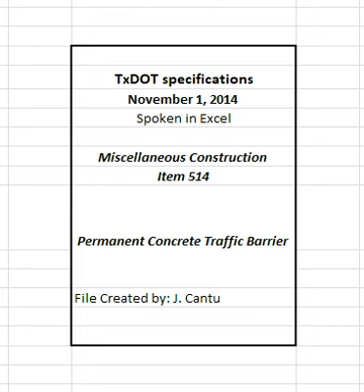Provide a wire line to maintain vertical and horizontal alignment of the slip form machine. Attach a grade line gauge or pointer to the machine so a continuous comparison can be made between the barrier being placed and the established grade line. Do not exceed the manufacturer's recommended speed for the slip form machine. Rails or supports at the required grade are allowed instead of sensor controls.